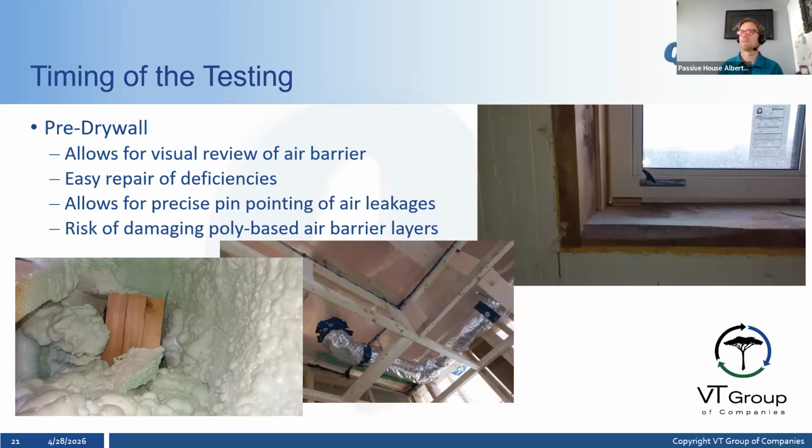If poly's missing, if there's a sealant missing, I'm able to see that rather than having to look through the camera. Then as I come down the house, I'm looking at the assemblies that are harder to visually assess specifically. So in this one here, you can see this. When I come to this assembly, I can look and I can see, yes, this doesn't look right, right? But when I have the pressure on, I can physically put my hand at this assembly and I can feel the wind, right? This is at a stairway, so I could physically put my hand and feel the wind.